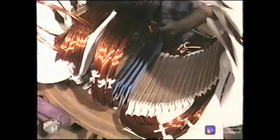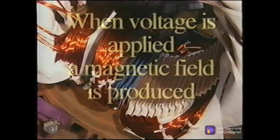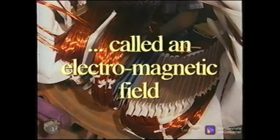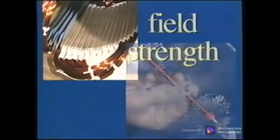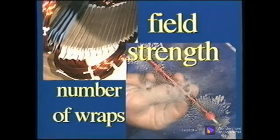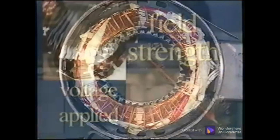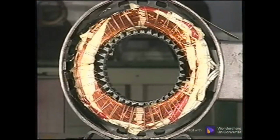In a motor, the coils are placed in the stator so that they wrap around a section of the laminated iron core. When voltage is applied, a magnetic field is produced, which is called an electromagnetic field. The strength of the field, or the force of the field, is dependent upon the number of wraps in the coil, the closeness of the wraps in the coil, the size of the coils, and the voltage applied to the coil.